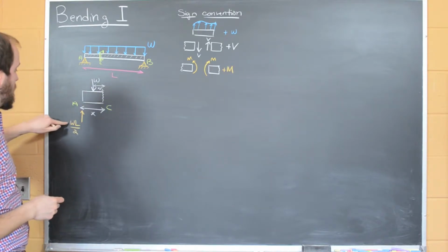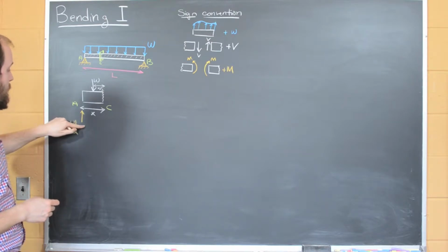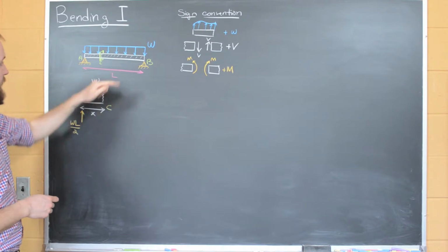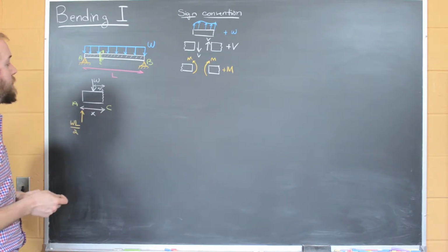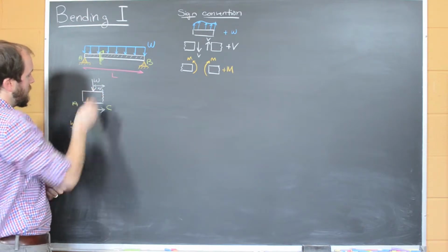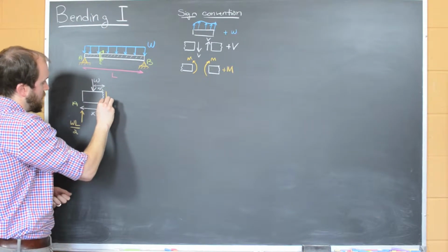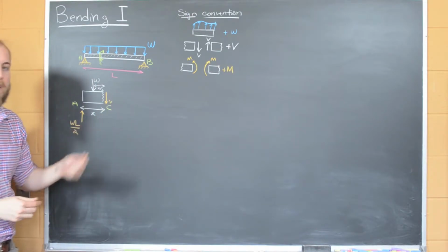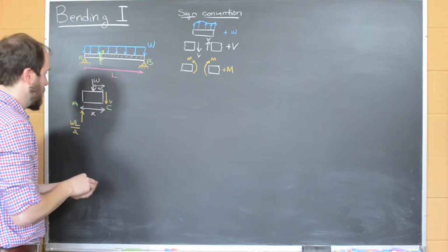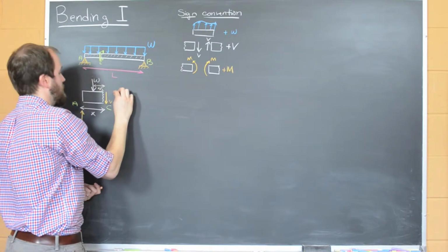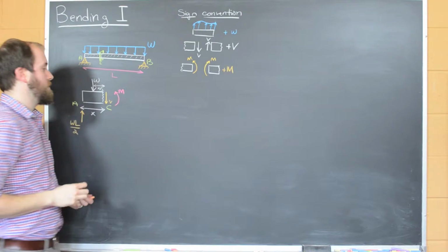It's basically the force times the length, and because there are two simple supporting boundaries, each reaction force is taking on half of this distributed force. We're pushing down here, which means there's going to be a shear force, V, where we made our cut. And this thing is going to bend, which means we expect there to be a moment, M, going that way.